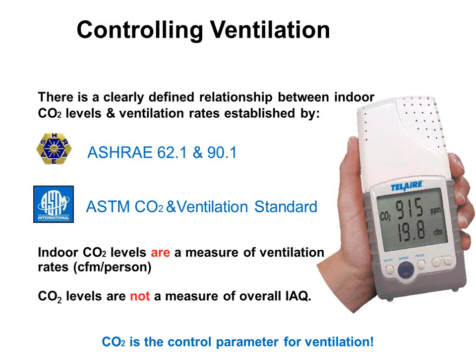A couple things to point out when we talk about these CO2 sensors. CO2 sensors are a measure of the ventilation rate. It tells you how much CFM you're bringing in per person. It has absolutely nothing to do, directly speaking, with indoor air quality. Sure, if I bring in more fresh air, I will dilute down pollutants and probably make your air quality better, but it's not a way to measure indoor air quality. CO2 does not tell you the air quality is good. You could have tons of pollutants going on in the building, and CO2 doesn't have anything to do with those pollutants, right? So you can have a bad building, and CO2 is not going to tell you that.